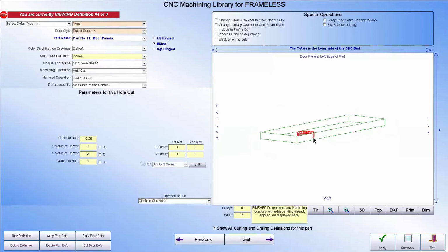The benefit, that's used a lot. Negative depths are used a lot in blind dado construction because we want to make sure that regardless of the thickness of the wood that we're using, we end up with a tenon of a given dimension. Maybe we always want that to be 3/8 of an inch or even 1/4 of an inch.